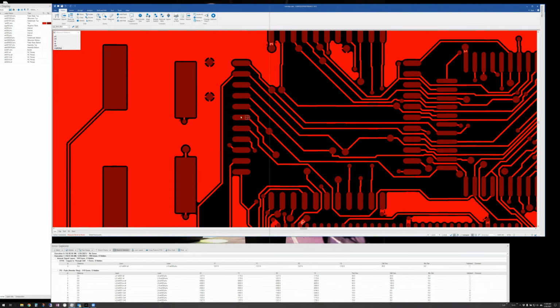You know, I've gotten to the point where I just get used to it and know if I click close to the center of this, that it's going to get the center. If I click way over here, it's not going to get the center. But if I click here, close to the center, and I follow the prompts down here at the bottom, it'll tell me what the distance center to center between two items is.